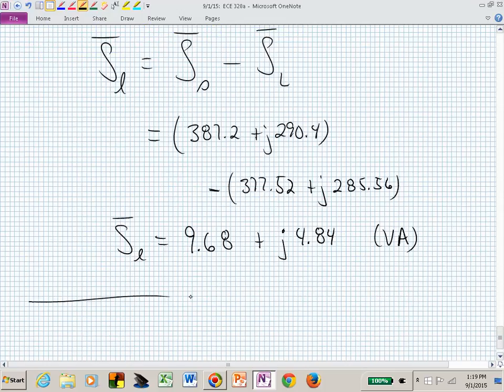And now do you see why you might want to elevate the voltage? If you're trying to supply some facility that's quite a ways away and you don't have very effective transmission lines and there's a lot of resistance in that transmission line, you may want to get the voltage really high so that the total power is still V I star, but the current is small so that your I squared R loss is small if you have this transmission line represented by a resistor.